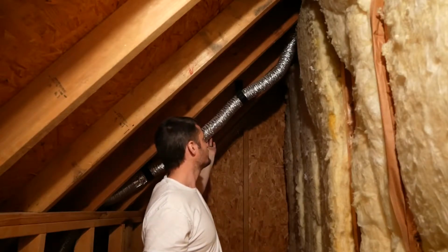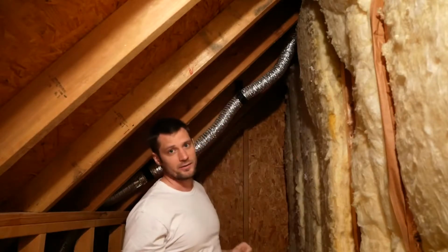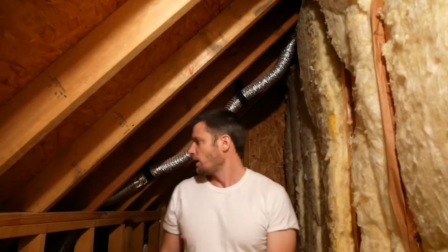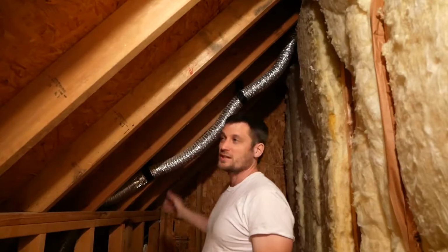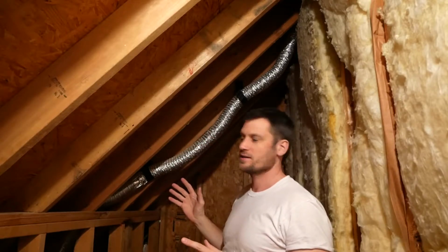So we're going to replace this here with an insulated duct, and then I'm just going to go ahead and replace that fan as well. And then where does this duct go? It doesn't actually exit out the roof, which is usually the best place to exit. It actually goes right out the soffit. So if we take a look here, we can see the duct runs out and just goes right out the soffit there. So let's go outside and take a look at that.